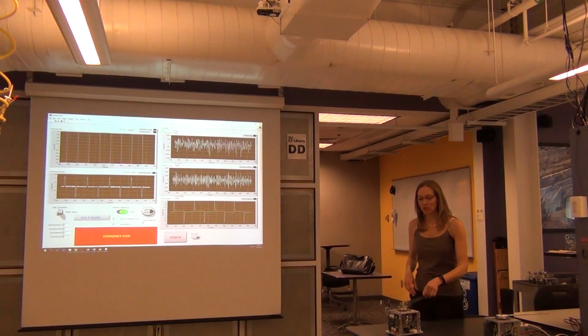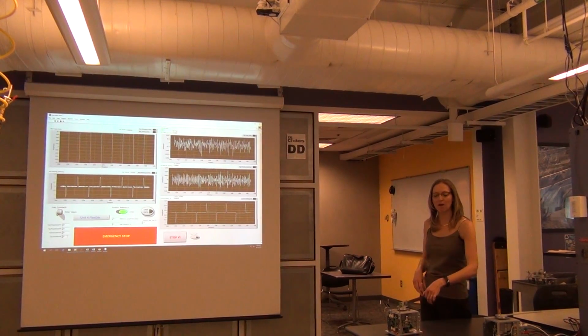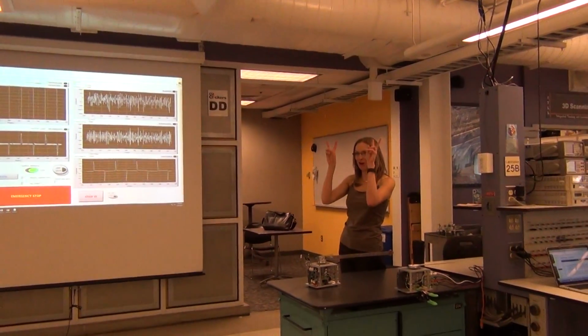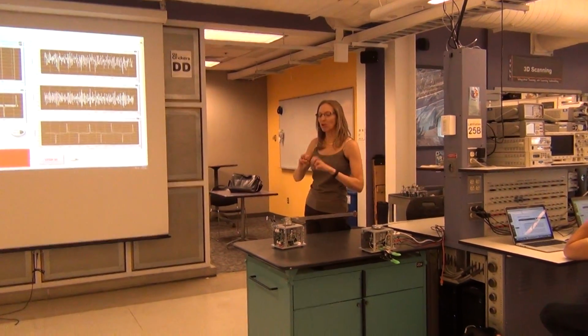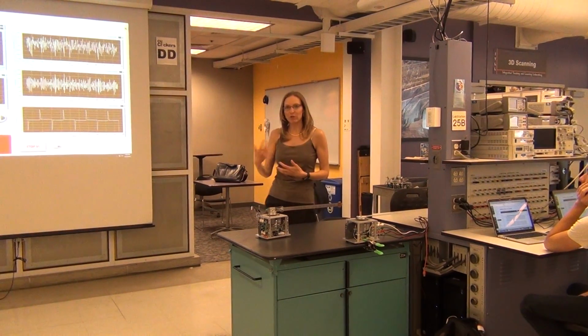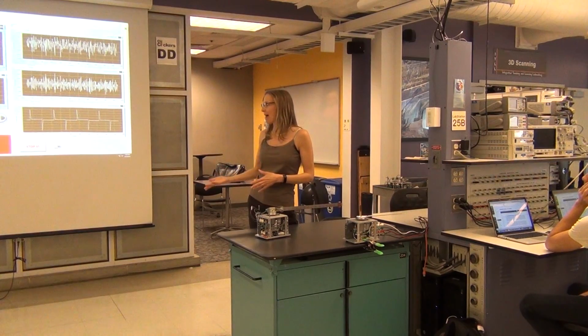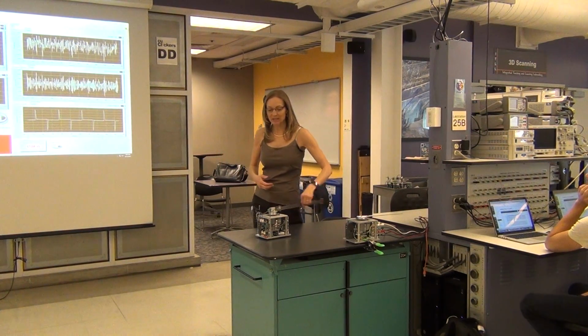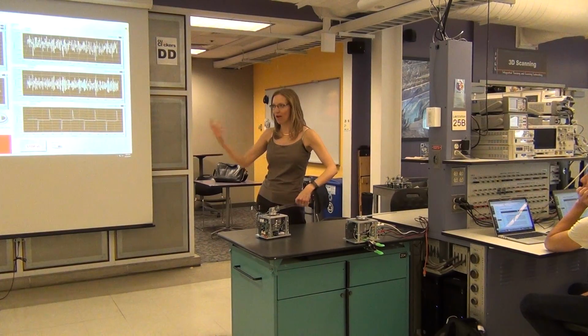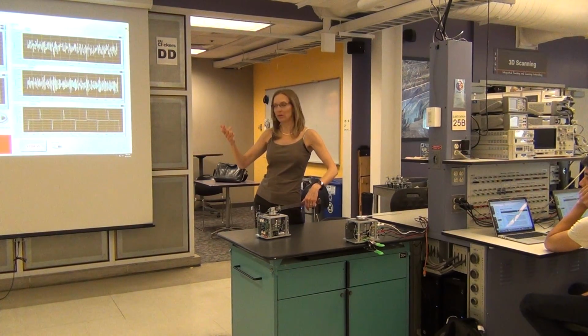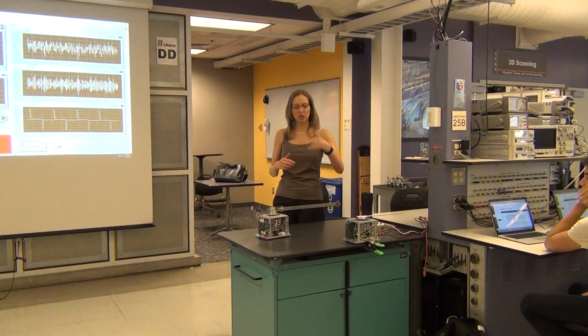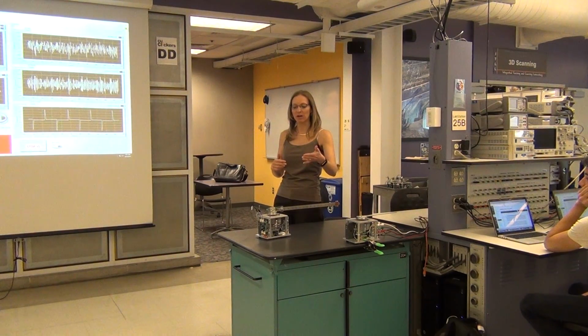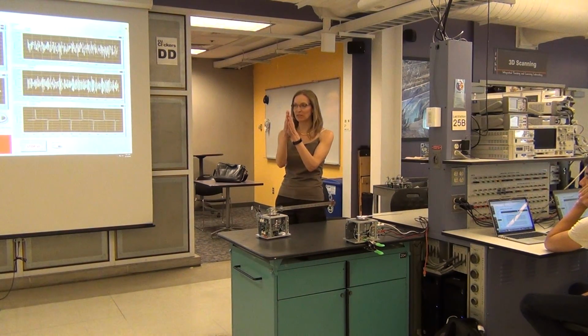So now we can actually make this flexible arm operate like a rigid arm. And we'll have you play around with, what if you just put gains in here and don't have K2, K4? How does it work? You'll see how much it oscillates because we don't have that feedback on the tip. And then once you implement K2 and K4, you can see how you can reduce that tip deflection down to almost 0.